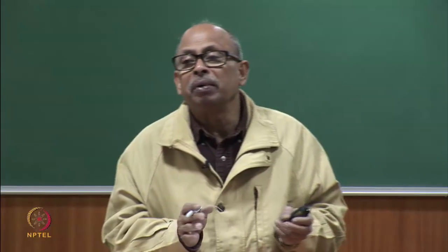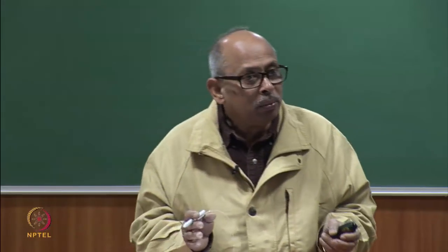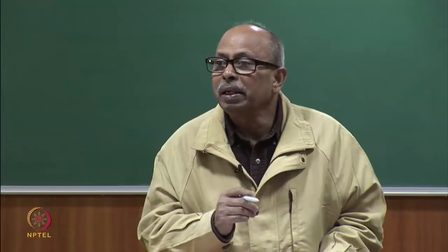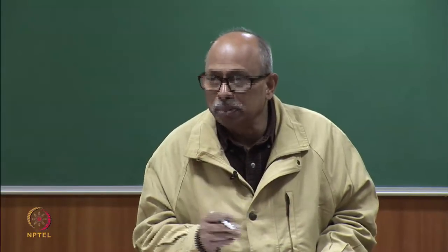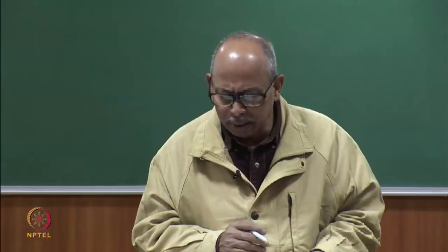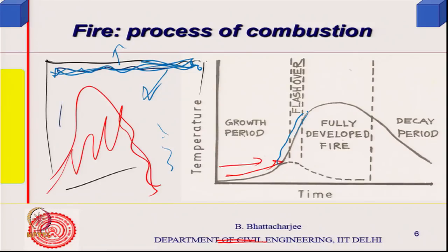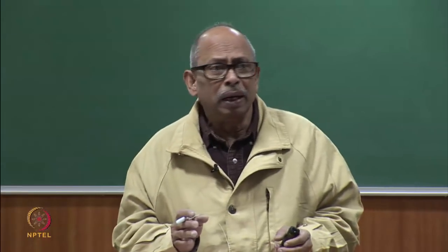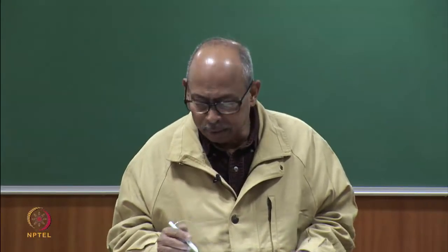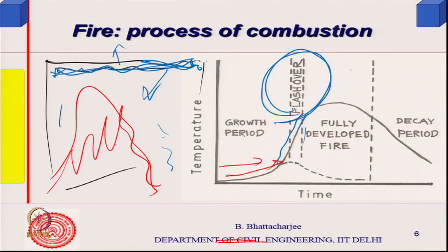More or less you will have some kind of uniform temperature in the whole room, and a time will come when the whole room will attain the ignition temperature of the combustibles, which on an average will be similar. Suddenly you find there is an increase in temperature. The point where this occurs, we call it flashover. This terminology is used in some other places also. So there is a flashover point. Flashover means everything now has caught fire.